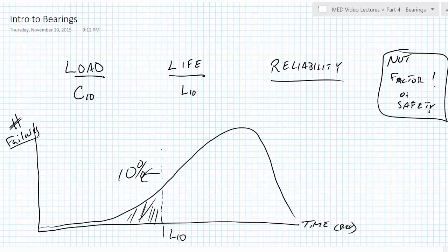This load life is actually calculated the opposite way. For a batch, when 10% of them have failed at a particular load, that's how you identify what the particular load rating is, but it's an equivalent way to think of it either way. Instead, we set it at a particular number of cycles, which is 1,000,000 inner cycles, and identify a C10 from that.